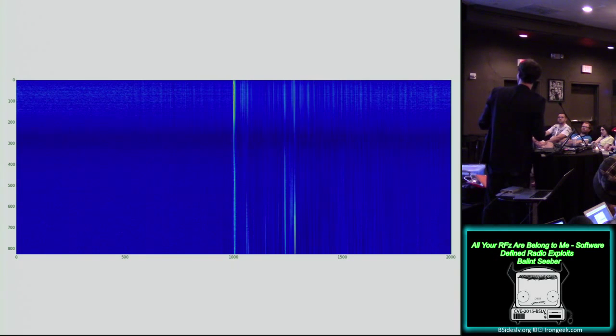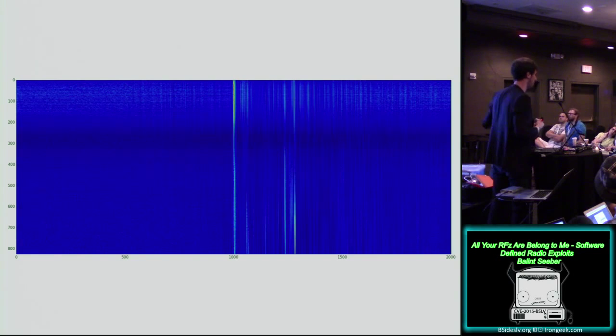And that's essentially the visualization of multipath, because you can see all the different signals coming in from the different path lengths that they have to travel through, propagate across, to get to your receiver. And so an equalizer is important because it essentially mitigates against all these signals that end up destructively interfering. Now, this is important for this system.